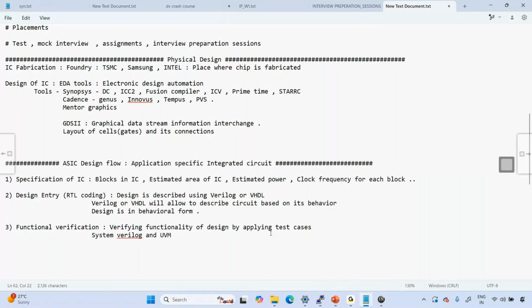Even in physical design they may fail. But failing here is not in terms of functionality. It is timing. Right? Timing is different. Timing means your design should work with the clock frequency you are using. For a 1 gigahertz clock, your design should work. So you are testing timing. If it is not working, then you have to tell your RTL engineer to come up with a simpler logic depth between two gates. You will understand that when we do STA. There is a meaning to it. So there is a chance that it may fail.